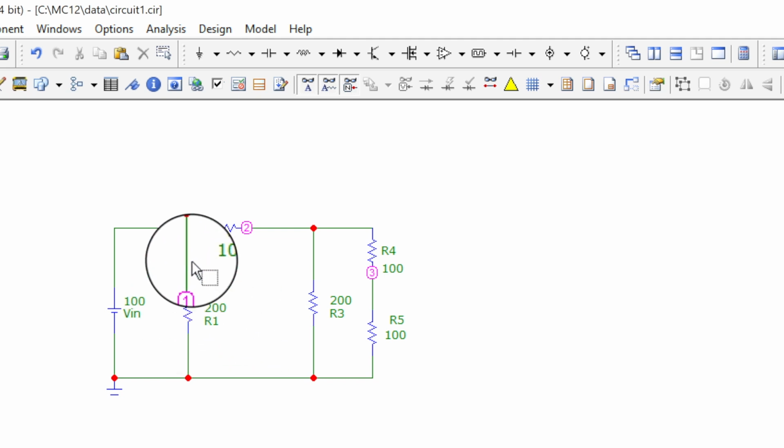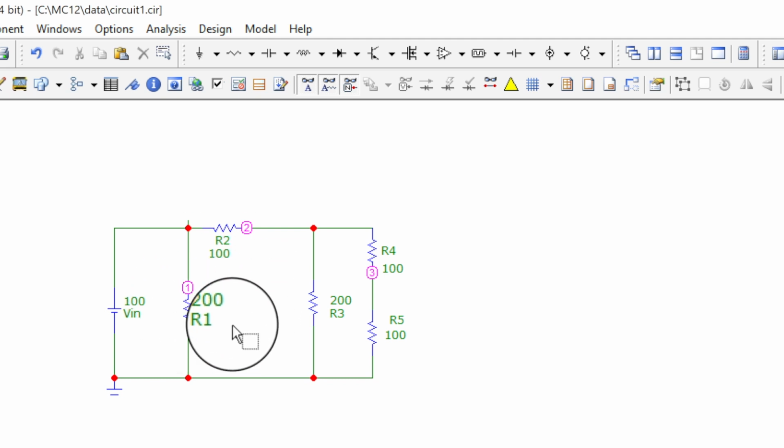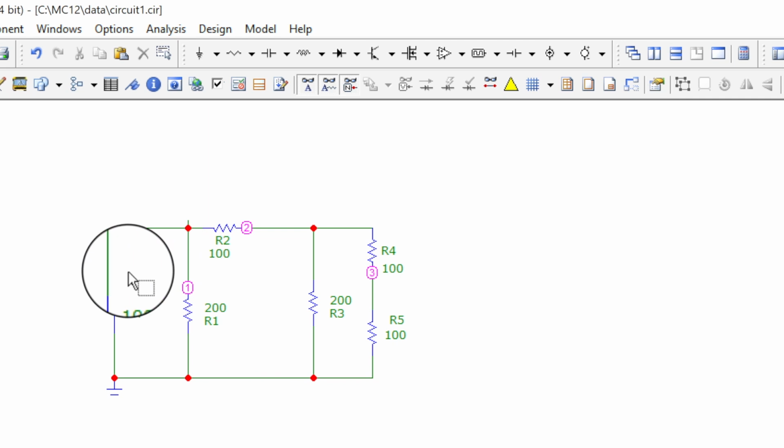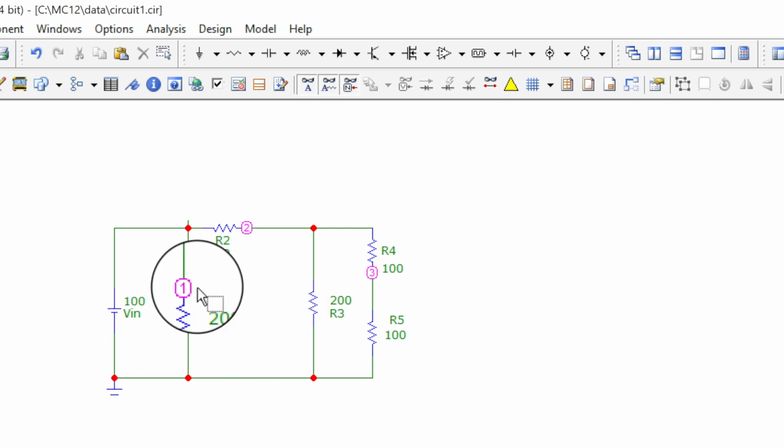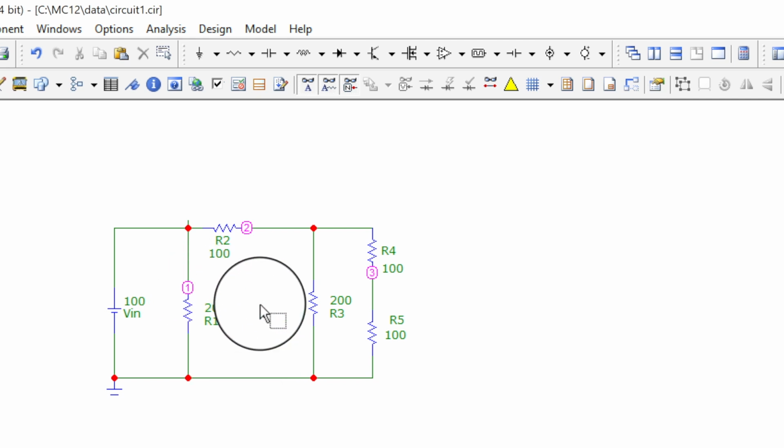And once you analyze the circuit, once you figure it out, once you simulate it, you see the current looks backwards. And if you pull the part away, now a transistor is more obvious, right? But a two-leaded part like a capacitor or resistor might not be obvious. And once you pull it away, you go, that's what it is. I thought the current was flowing this way, so I put my part in a certain way, and it turns out it's going the other way.